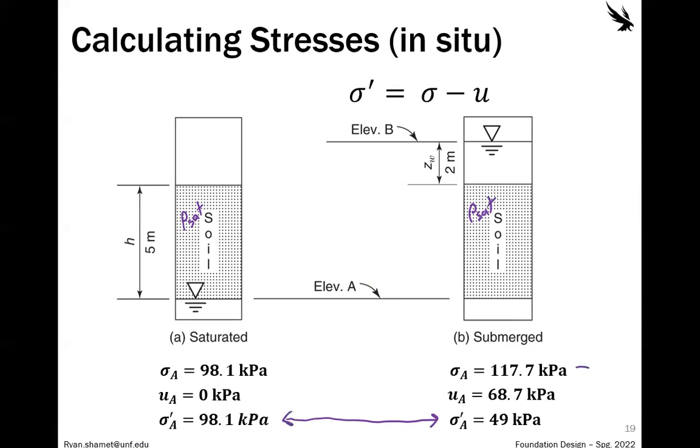So although the total stress increased, that groundwater table plays a big role. If we were designing just off of this value, we'd be like, okay, good, the water table goes up, we're good. But then if it goes down, we are obviously losing that stress value, and that changes our strength. That's why we always design for the effective stress down there.